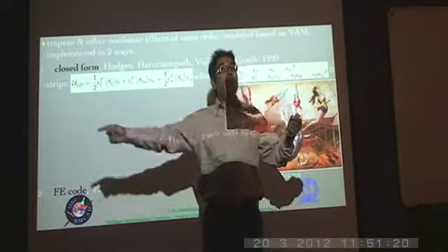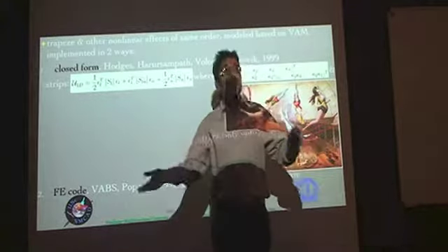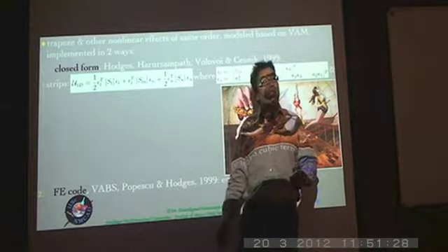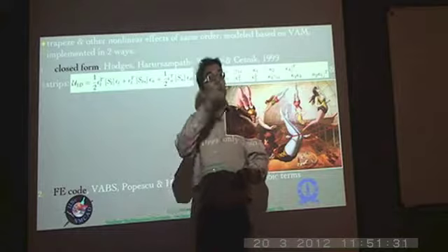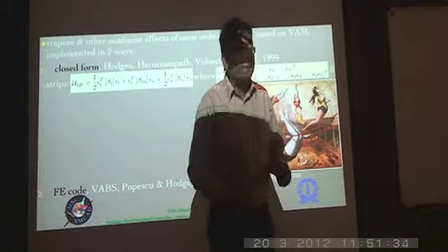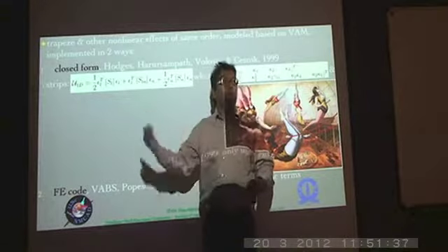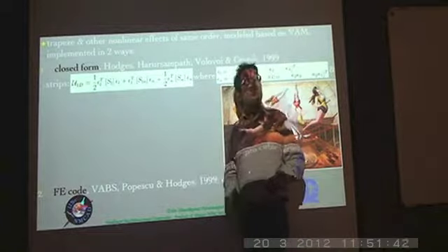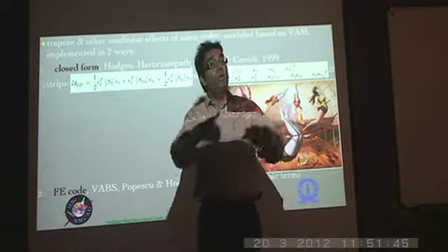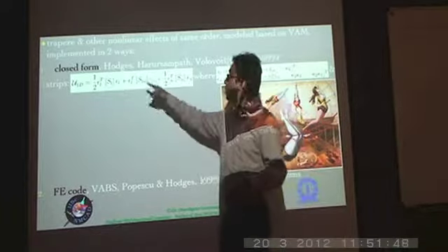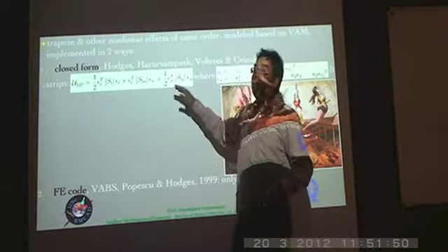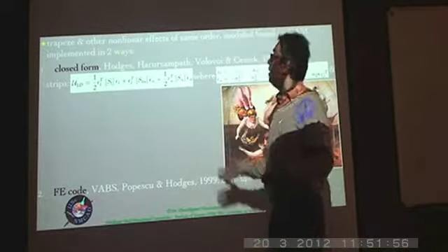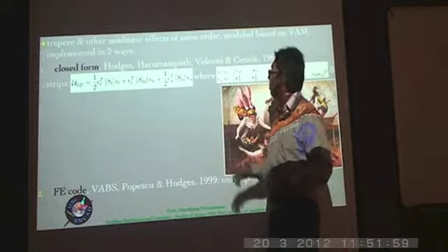Of course, there is a finite element analysis of the reference curve, which is the 1D analysis, which we have to do later. But even the cross section analysis itself, in the case of complex geometries and material distributions like airfoil sections, has to be done by finite element analysis. In other words, you will discretize the cross section into 2D finite elements, quadrilateral, triangular, whatever you want, the typical way of doing a 2D meshing, and then you apply the asymptotically correct solution in order to determine the cross-sectional stiffness coefficients. Whereas in this case, you have actual expressions in terms of those geometric features and those material properties, and then you can evaluate each one of these matrices.